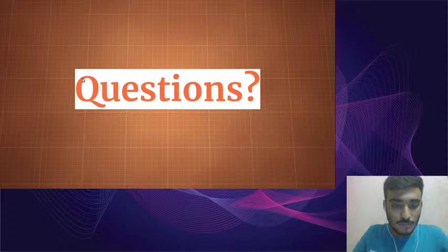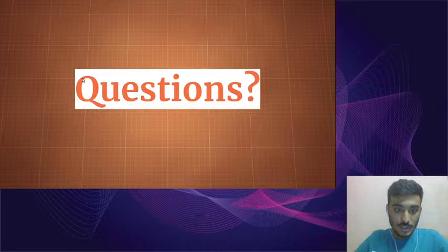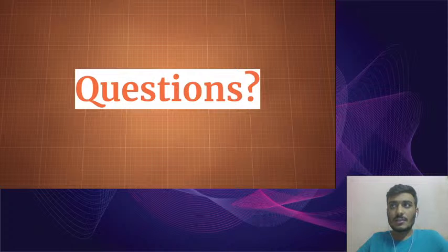Okay, a question has cropped up: in which scenarios do we use which motor? An example would be appreciated. You might remember the 3D sketcher which was introduced to you in the orientation session. In that we used a different kind of motor called a stepper motor, if I remember. We needed greater accuracy while sketching the portrait, so we needed to perform the operation in steps to have greater precision. Stepper motors allow us that, but the disadvantage, as far as I know, is that stepper motors are a bit bulkier when compared to servo.